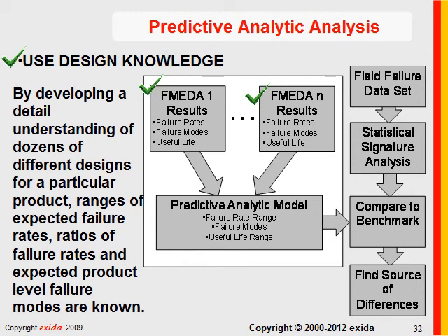failures at a particular site are not due to inherent failures of the product. Some of them are due to inherent failures of the product, and some of them are due to maintenance-induced failures. Human beings cause the failure. This was covered in the FMEDA seminar last week. You can see a copy of that, but the bottom line is at Exida, we use FMEDA data, which is more conservative than real-life data. Plus, we model maintenance capability and site-specific failure rates separately.